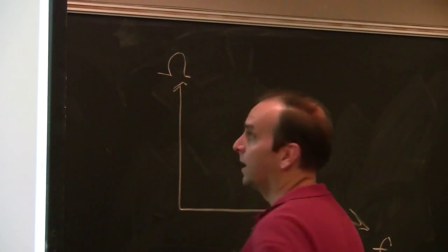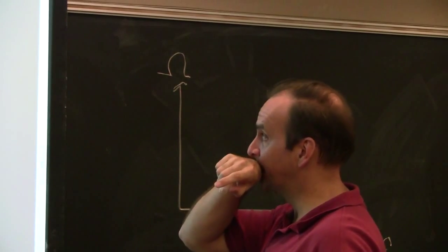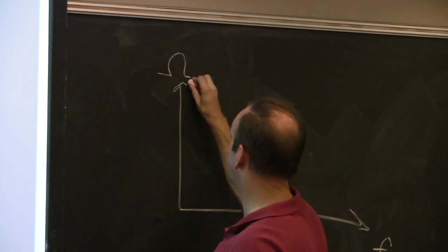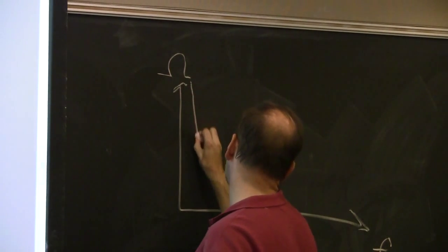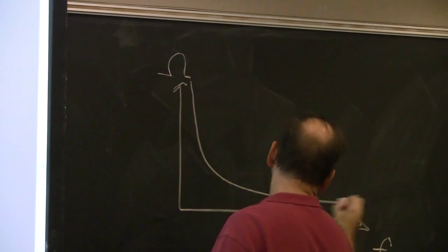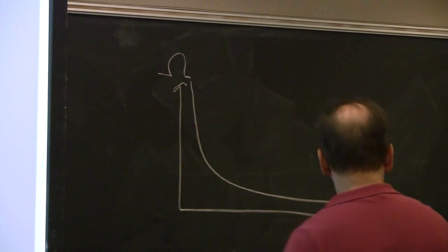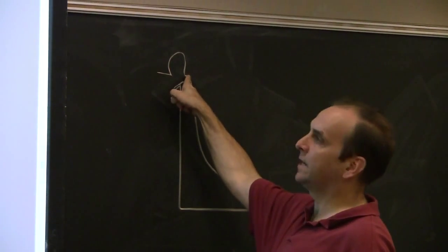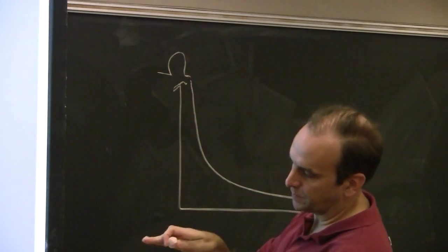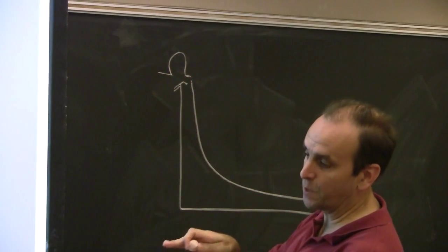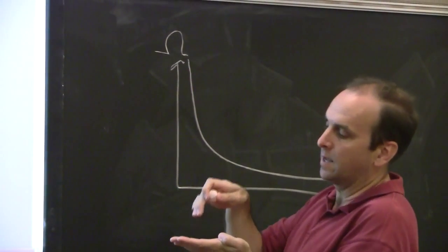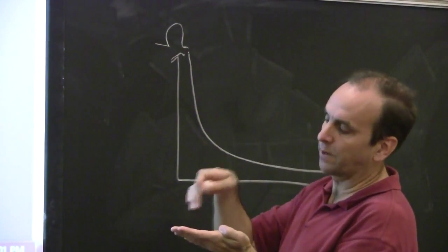Now, I didn't really talk about this, but the impedance of an ideal capacitor at very low frequency is pretty much infinite. So it kind of looks like this. That's an ideal capacitor. And that says that it starts off at infinity because, remember, there are two parallel plates with a dielectric. There is no way for DC current to get back and forth. In fact, there's no way really for electrons to go from plate to plate.